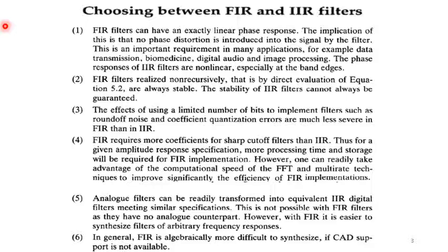We use FIR filters when we need exactly linear phase response. That means there will be no phase distortion introduced into the signal by the filter, and this is an important requirement in many applications.